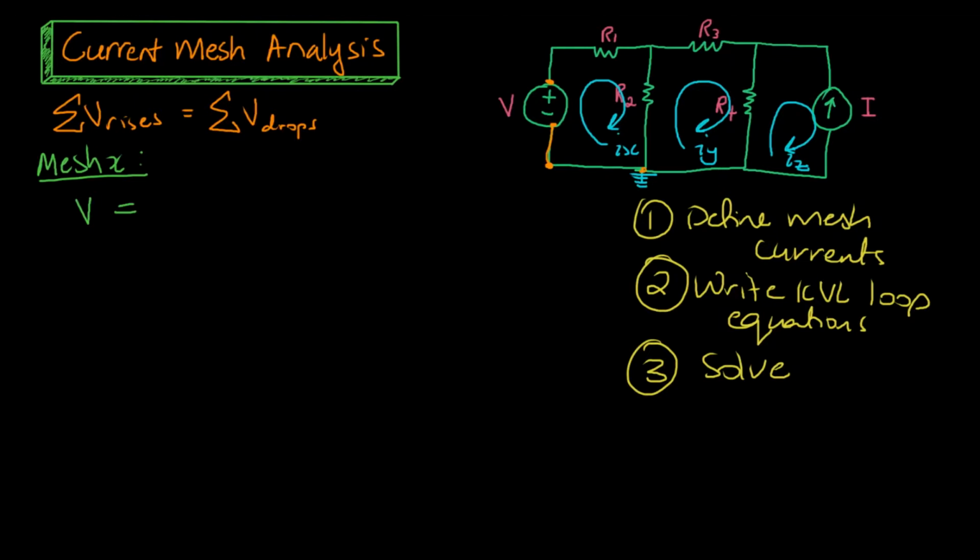We then continue tracing this current around up to our resistor. Resistors are defined as voltage drops. That is their definition and their purpose inside of a circuit. A voltage drop is always current traveling from high potential to low potential. So we can draw on positive and negative terminals here to show that voltage drop. To find the voltage drop for this resistor, we use Ohm's law, V equals IR.